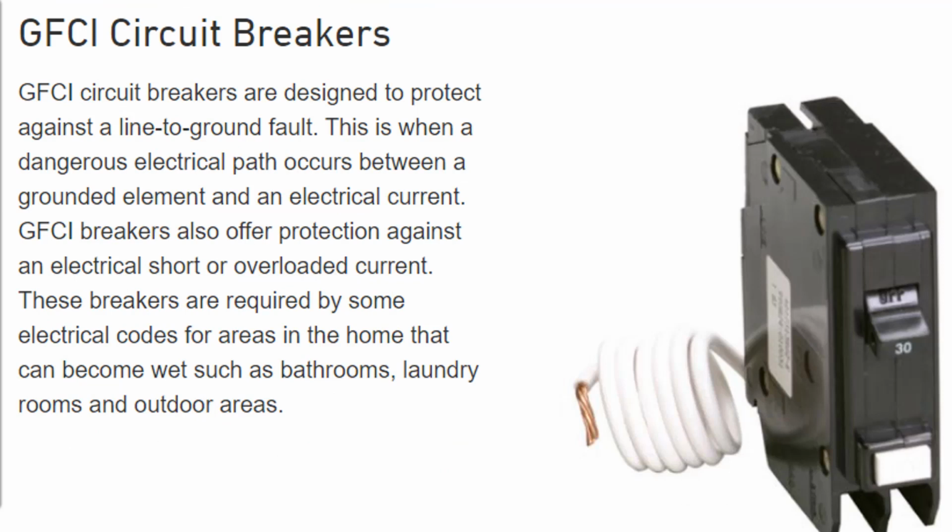Next one is the GFCI breakers. They are designed to protect against a line to ground fault. These breakers are required by some electrical codes for areas in the home that can become wet, such as bathrooms, laundry rooms, and outdoor areas.